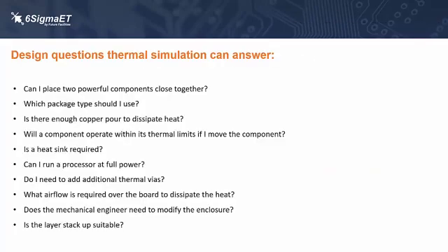And these are just some of the design questions that thermal simulation can help you answer. So for example, can two powerful components be placed close together? Is there enough copper in the board to dissipate the heat? Do I need a heat sink on this component? And I'm sure you can think of many more.